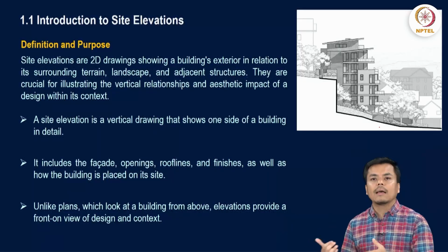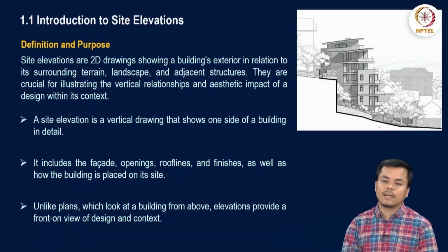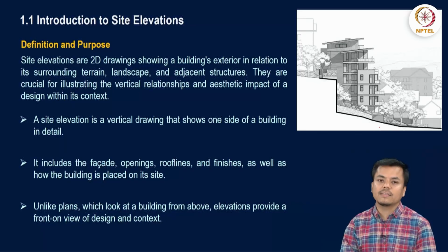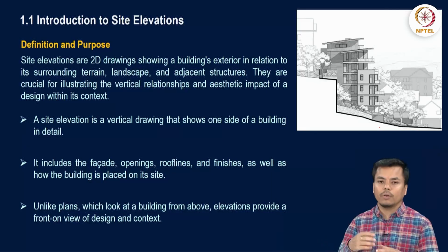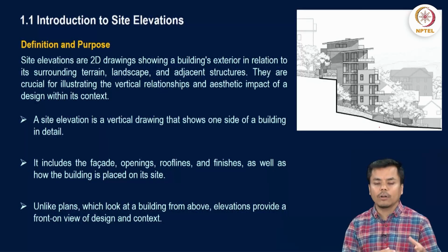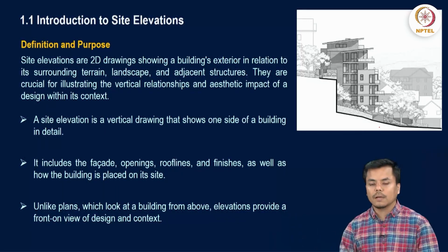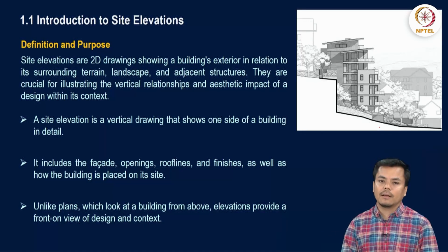That is where drafting a site elevation helps others understand the site plan. The reason we draw the site elevation from the site plan is that we just have to project the lines from your site plan according to the direction and then draft the site elevation.